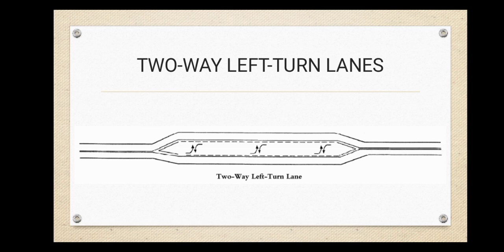For the option of paved shoulders, no effect was noted, whereas for the other options, reduction in fatal and injury crashes ranged from 30 to 85%. Since the results are site specific, the operational treatment selected may not always be appropriate, and specific site studies are required.